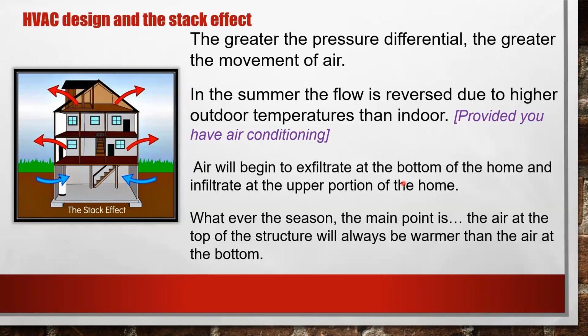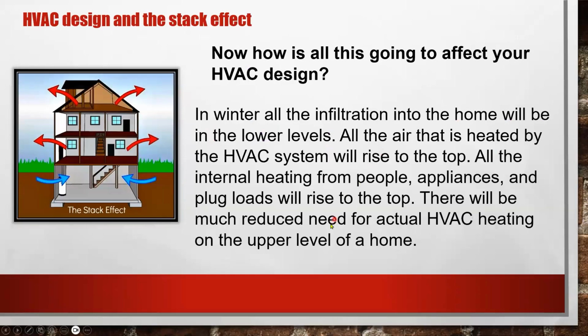Air will begin to infiltrate in heating at the bottom of the home, and in summer infiltrate in the upper portion of the home. But no matter what season we're in, the main point is that the air at the top of the structure will always be warmer than the air at the bottom of the structure. And you've probably all had to deal with homeowner complaints around this.